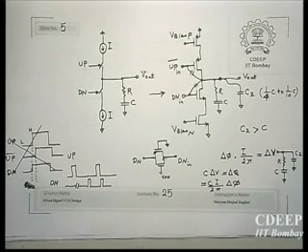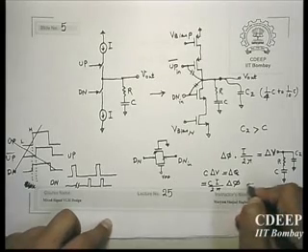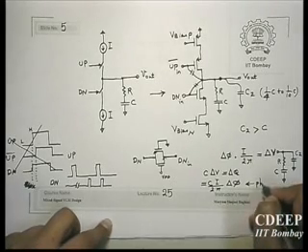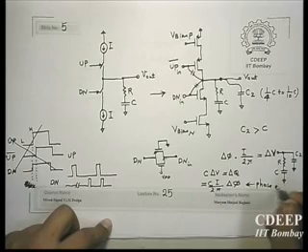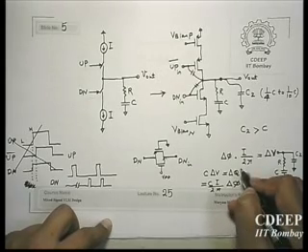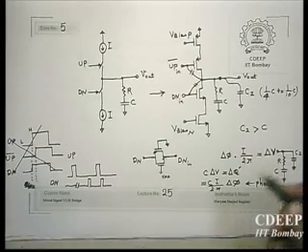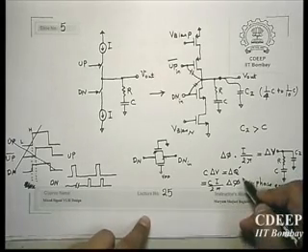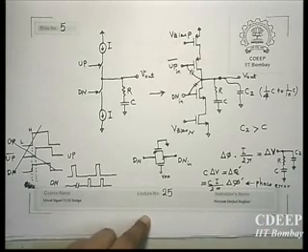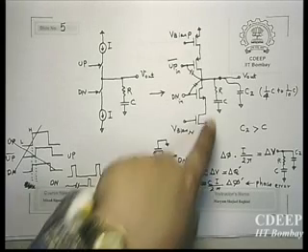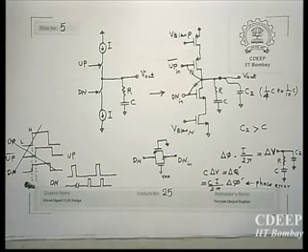So this is called phase error, right? This delta Q I'm talking about, maybe I call it delta Q dash. It is not that common delta Q; this is the error we received because of charge which was on C and was supposed to get discharged by I sink, but it didn't.